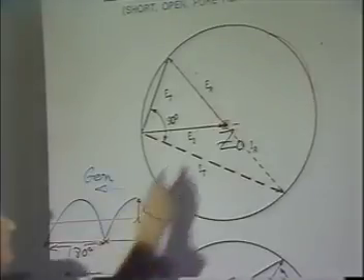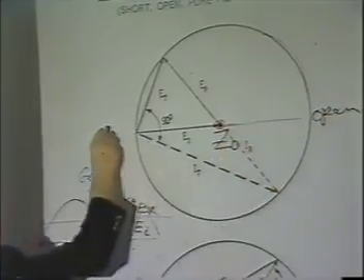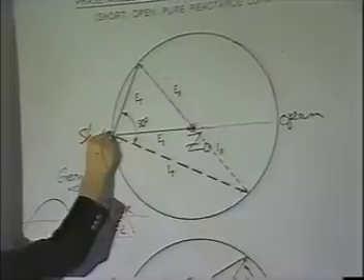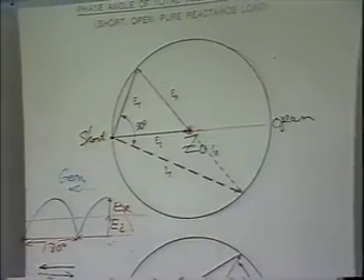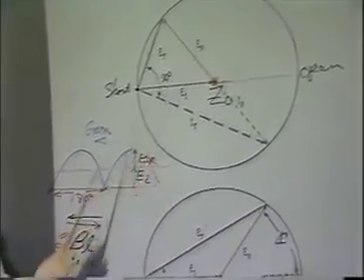What do we have over here? Open. What do we have over here? Short. Very important that you realize you are not getting away from your theory of reflections at all. You looked at them in terms of batteries and waves going down the line. Now you're looking at them in terms of sinusoidal signals. But still you are dealing with the phase of E sub R with respect to E sub I.